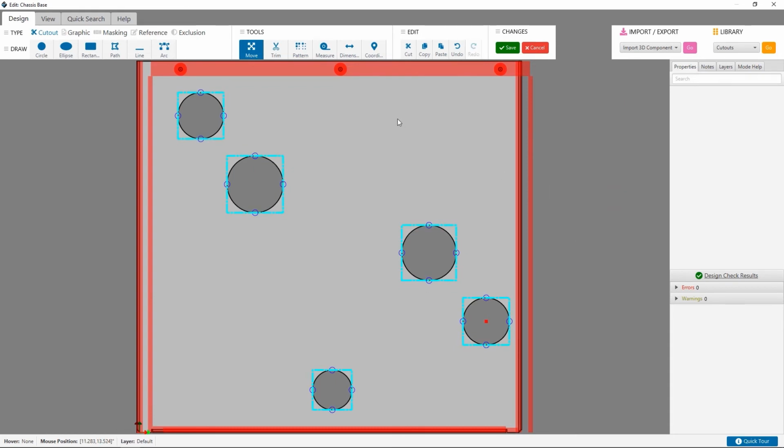So, in summary, the alignment button functions by comparing all of the objects in your selection to the first object you selected and aligning a specific point on them based on which alignment button you choose. The Distribute button functions by looking to the two objects on each outermost boundary of your selection, either the left and the right for horizontal distributions or the top and the bottom for vertical distributions.